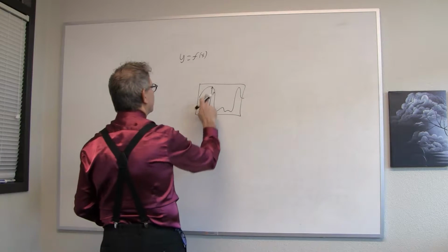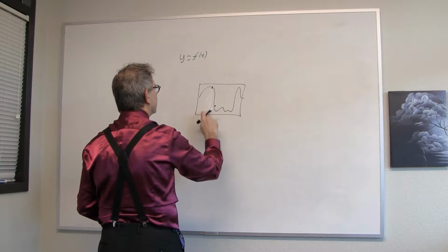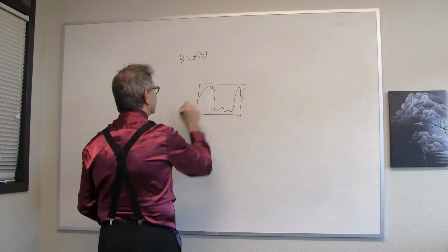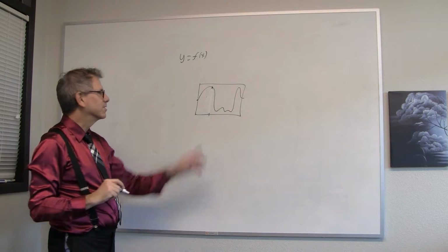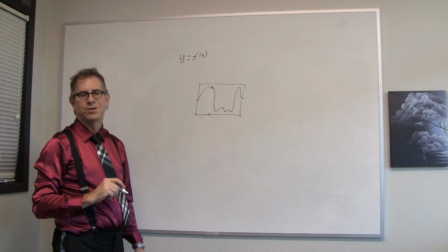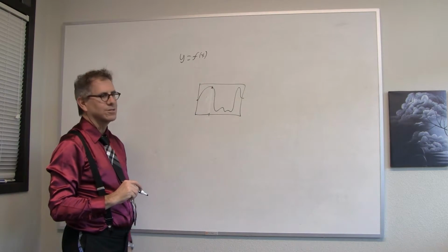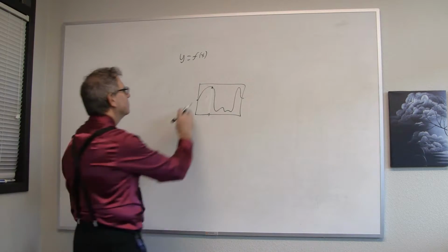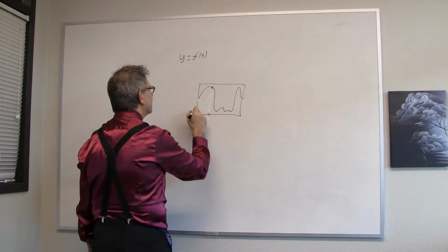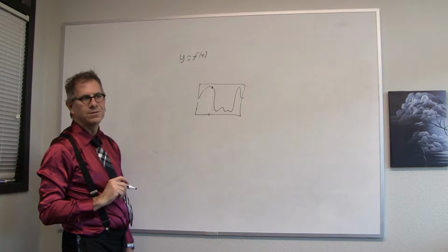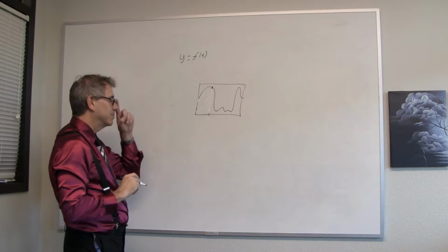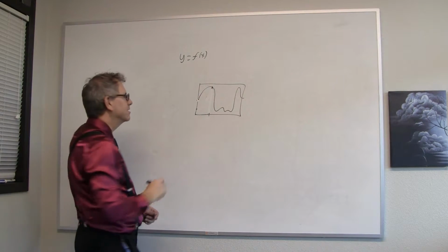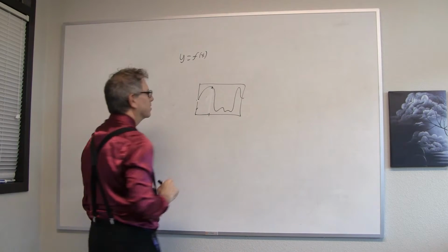So you go into C mode, here's what this daemon does. It starts over here on the left, and it looks at the place where the ink is. It looks at the value of this waveform at x equals 0, and it sets the output voltage accordingly. At the same time, it erases this and it takes the incoming voltage and puts a mark right there. And it moves over a little bit and looks at the value that's here and sets the output accordingly, and takes the input voltage and puts a little mark here.